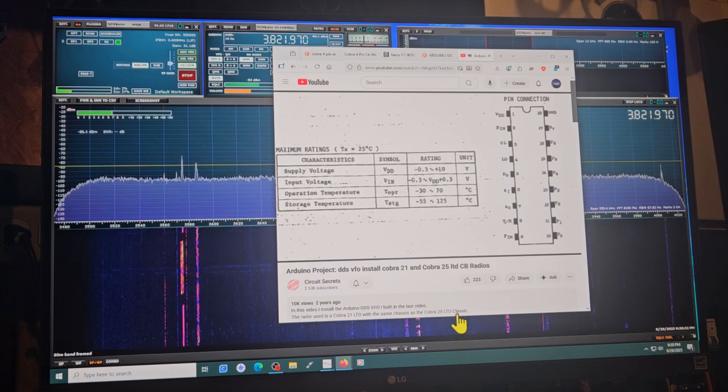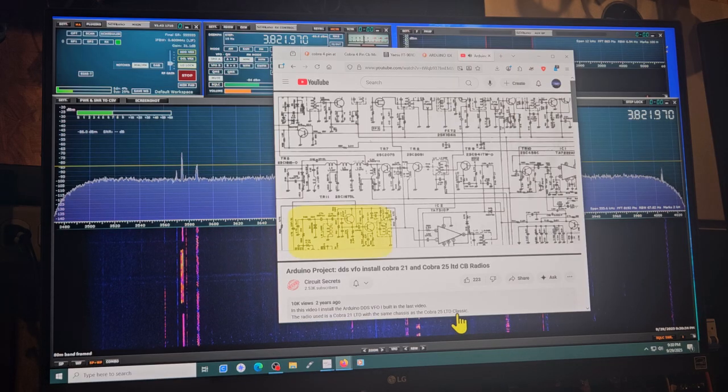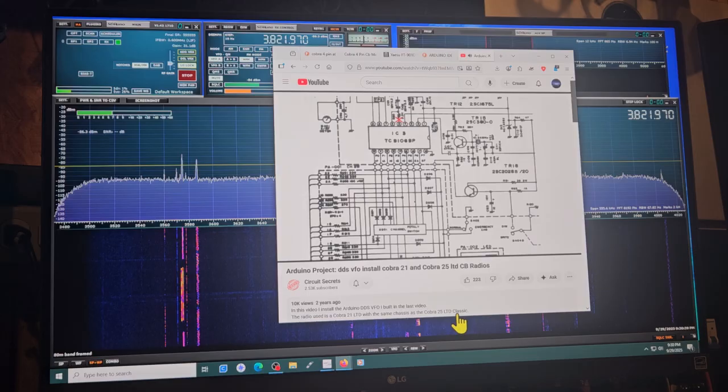With this information, on the schematic I can show you the plan to install the VFO. This is the VCO, so I will remove the transformer that is the last stage of its circuit before mixing. I will sever the PLL's connection to the VCO so it does not wildly change its voltage trying to lock, which could generate unwanted noise. I will sever the connection between the LD pin and the rest of the circuit. I will run a jumper from the PLL's supply voltage to the circuit normally controlled by the lock detector pin.